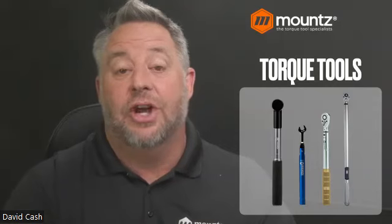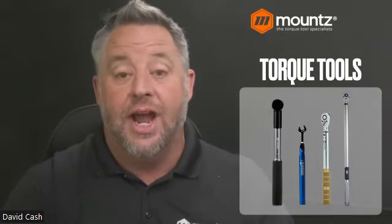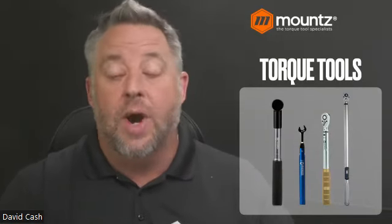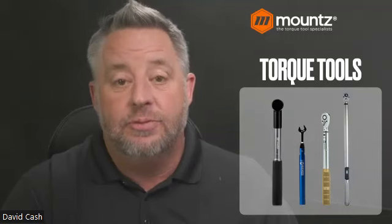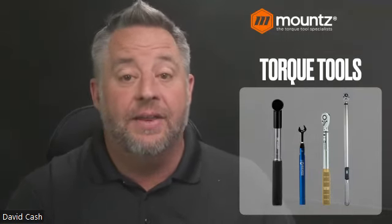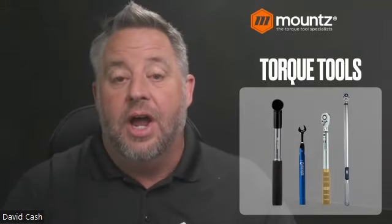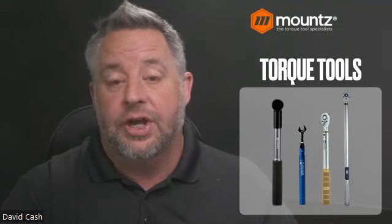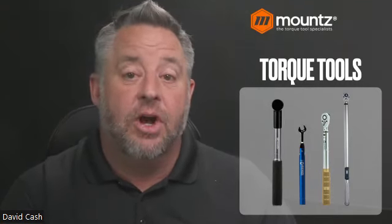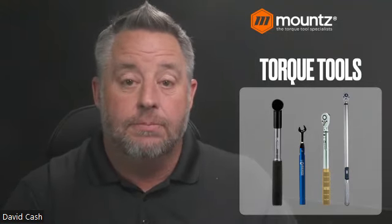And so it just depends on who's using that, how much torque is being delivered to the application with the use of a click wrench. Again, it's a widely popular wrench, very inexpensive, but it's highly influenced by the operator. So if you do see areas where you're having over torque issues of fasteners that may be failing, and there's a click wrench involved, the operator is usually the issue there.